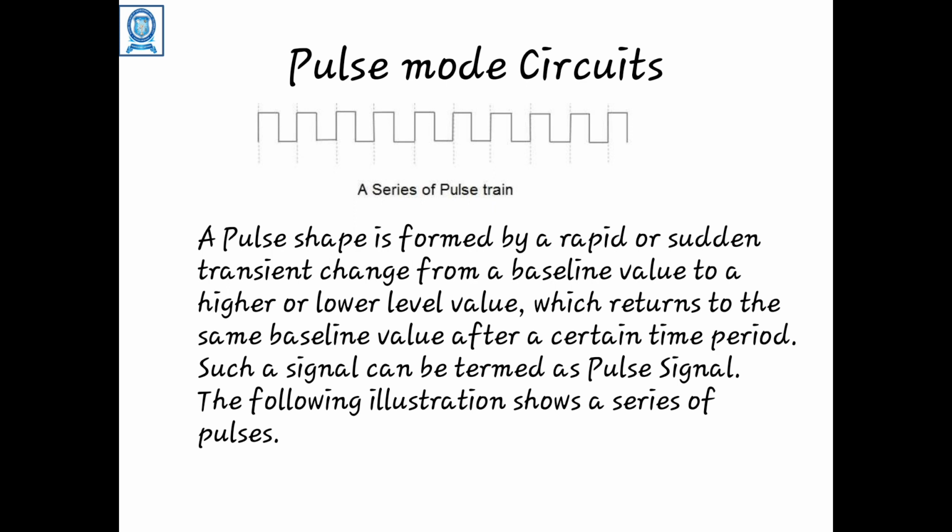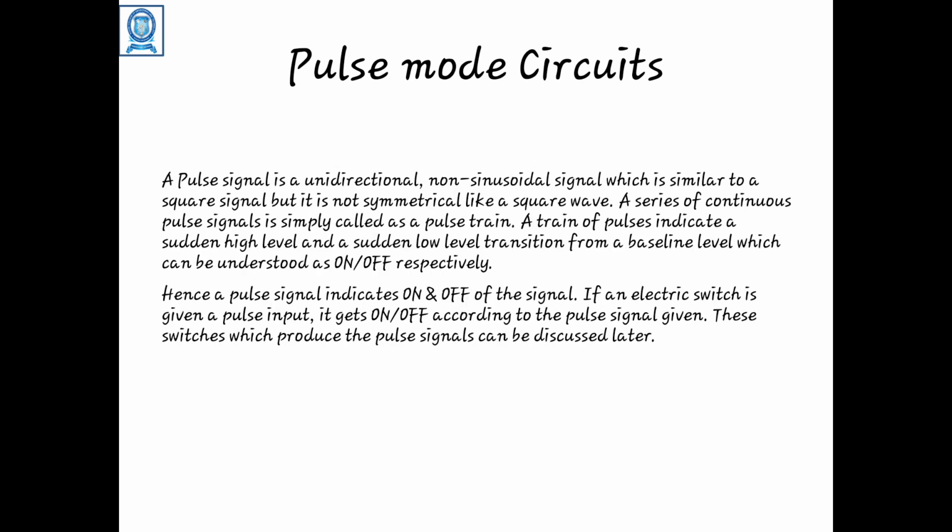The width of the pulses is long enough for the circuit to respond to the input. Also, one more important point for the pulse mode circuit is that the pulse width must be so long that it is still present after a new state is reached. So, pulses should not occur simultaneously on two or more input lines.